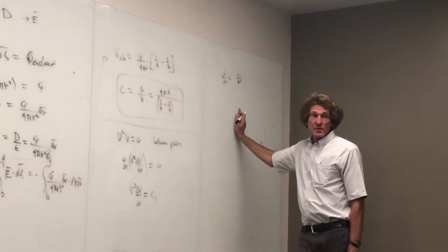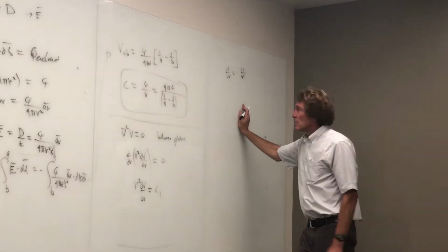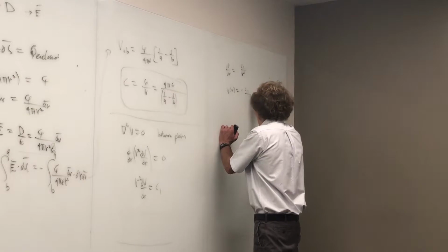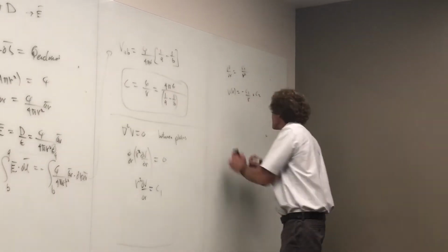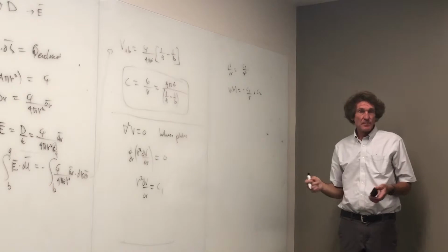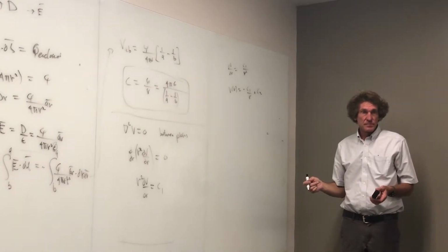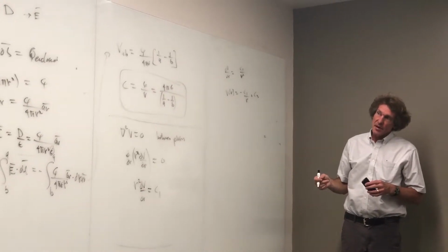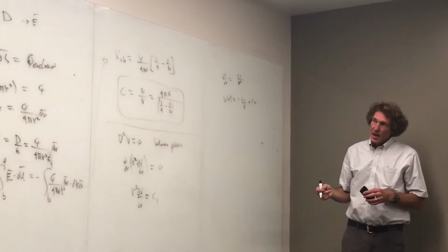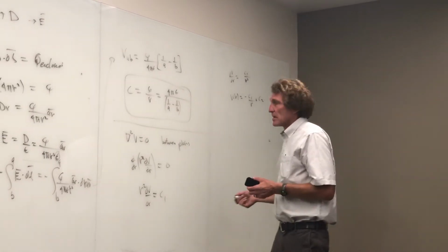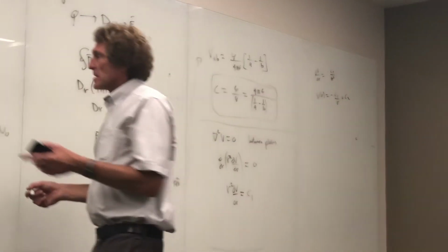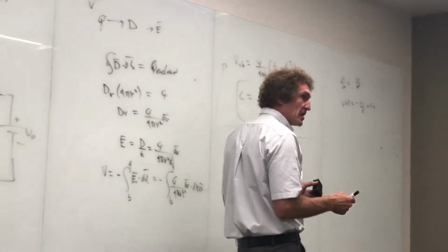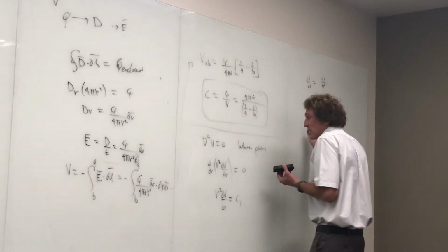And then I do another integration, follow me? When I do the next integral, I get V of r is equal to minus C1 over r plus C2. Agree? Now that's the equation for voltage anywhere between the inner radius and the outer radius, between A and B. Now you can do it this way. I calculated the voltage difference after I assumed charge. Now we're going to calculate charge, based on the assumption of voltage.